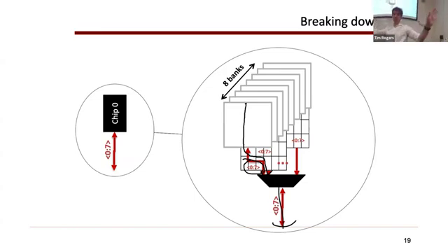It says, here's my physical address. So this is after virtual. Virtual is a software thing. Forget about those guys. I've already got the physical address. I have to take each of those bits of the physical address and say, okay, these bits tell me what rank I'm in, and these bits tell me what channel I'm in, and these bits tell me what bank I'm in, and these bits tell me what row. That's essentially the mapping that has to happen here, because the real memory system has to deal with this complexity, right? It is a big parallel system with a whole bunch of stuff happening at the same time.